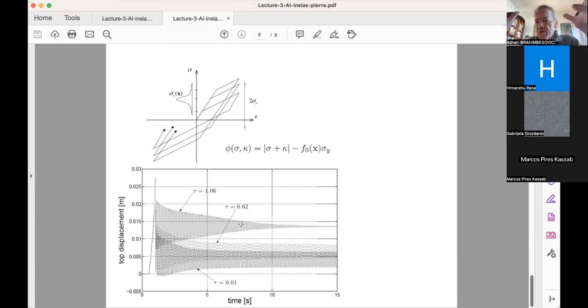So unfortunately, you could never take the whole 737 and crash it in some kind of test. And more importantly, it gets damaged because of turbulent flight, not because somebody is doing static testing. So since you cannot test this in the real size, you have to rely on tests on small-size specimens and then extrapolate these results to the real structure, which always carries doubts in terms of handling the size effect properly.